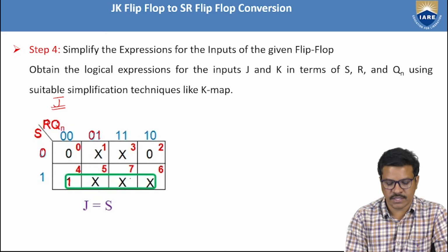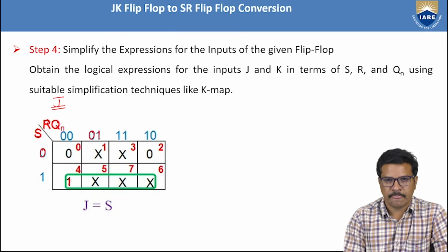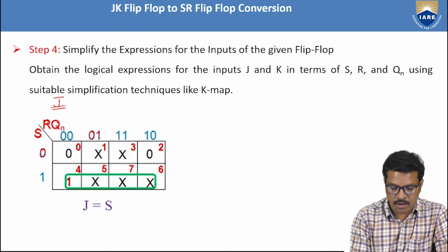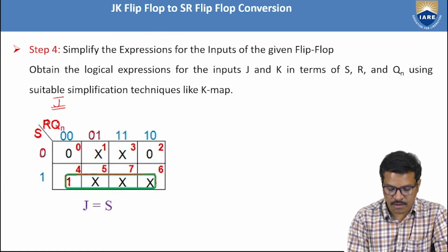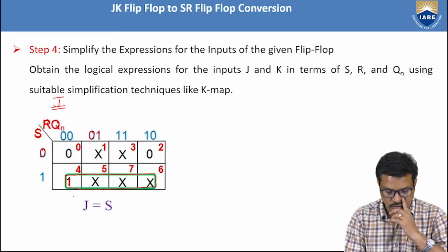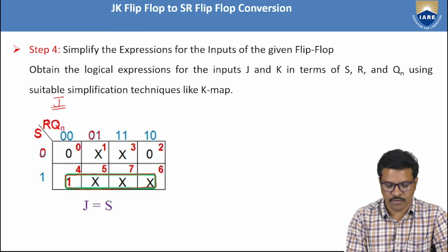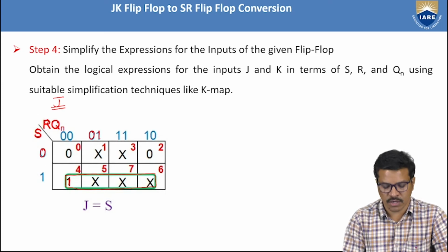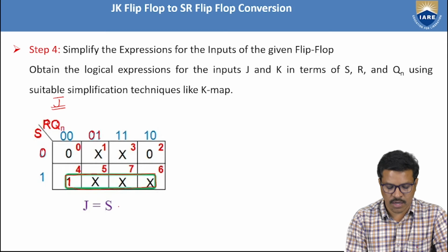Remaining 5 don't cares and remaining 2 zeros. By placing all the J column in the 3-variable K-map and making the prime implicant, this one quad, there are no ones left. Even though there are 2 don't cares, we are focusing on logic ones in the boxes, so it is already covered.